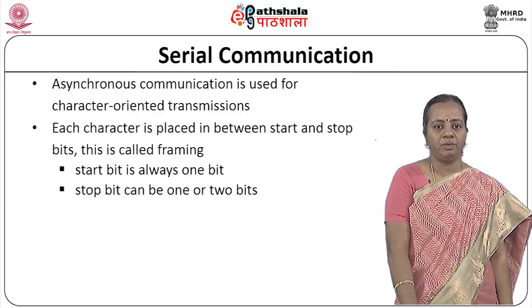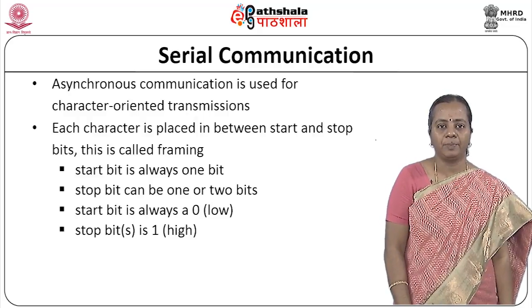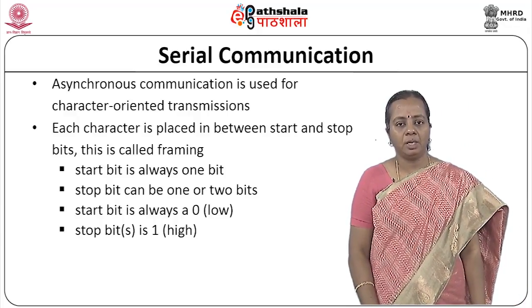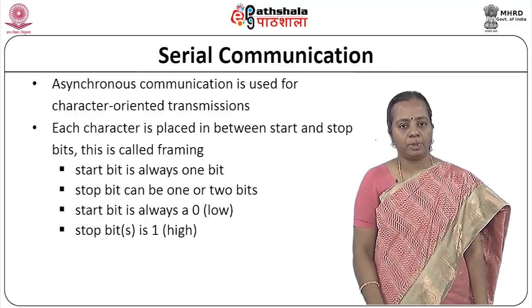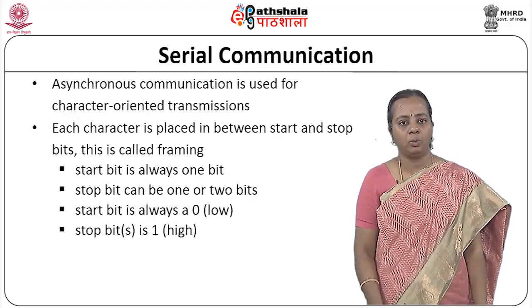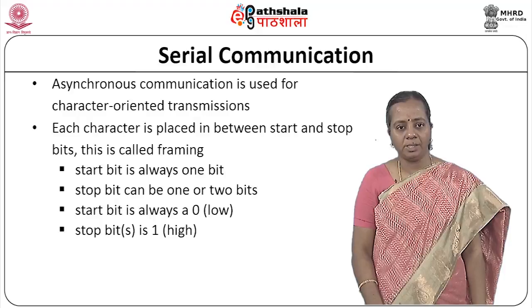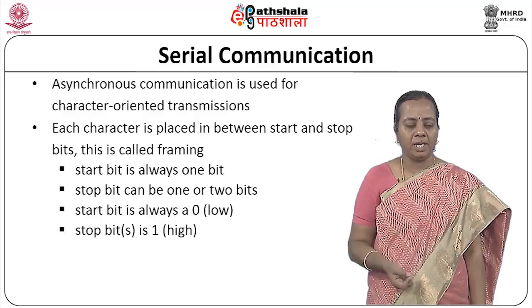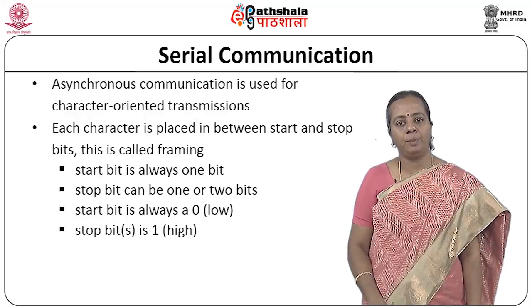With respect to 8051, I have shown that it has a built-in UART. The UART supports serial communication; without that you can't do anything in serial communication mode. In this we will be using asynchronous communication, which is used for character oriented transmissions. When you are sending a character, that means a single byte, it is placed in between a start and stop bit. So when sending asynchronous communication, a single byte at a time, I will be attaching a start bit and a stop bit.